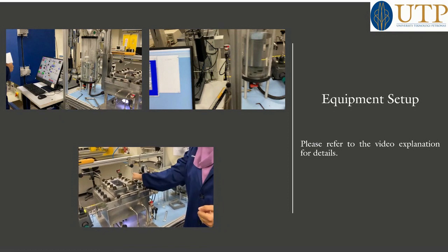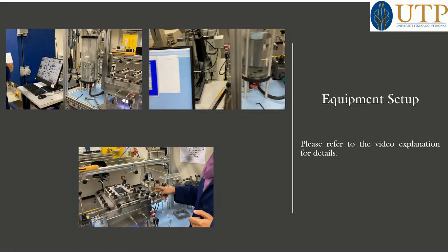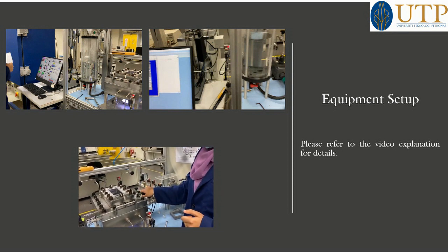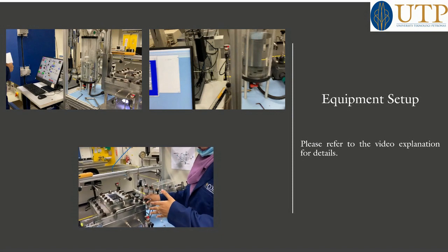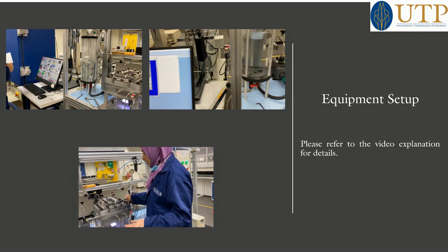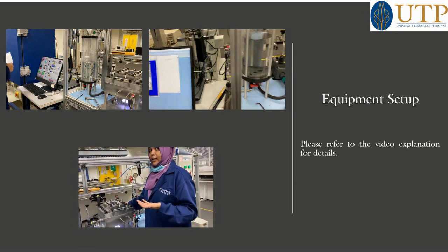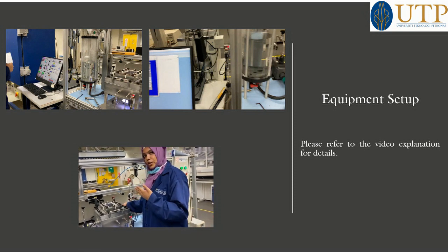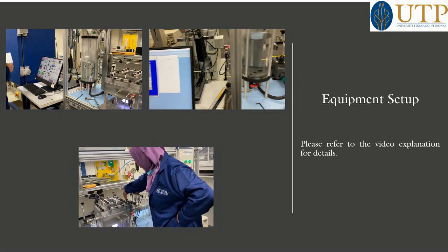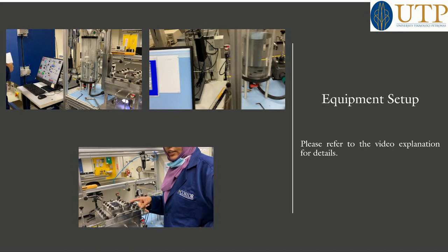Suppose I want to change the fluid flow from brine to oil. I can change it anytime. Like now, if I want to change it for my oil, I can. But if I want to change it for my carbon dioxide gas, I can't, because I already set the pressure for carbon dioxide at 150. That means if I open this one, it will hit my micromodel with 150 psi pressure directly.